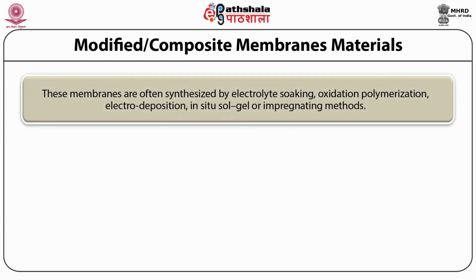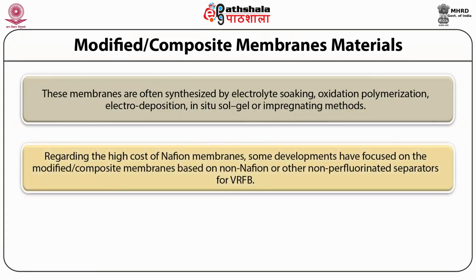These membranes are often synthesized by electrolyte soaking, oxidation polymerization, electrodeposition, in situ sol-gel, or impregnating methods. Regarding the high cost of Nafion membranes, some developments have focused on the modified or composite membranes based on non-Nafion or other non-perfluorinated separators for VRFB.